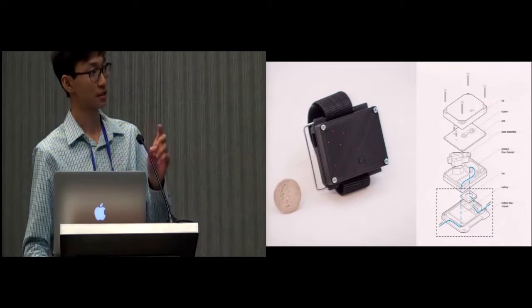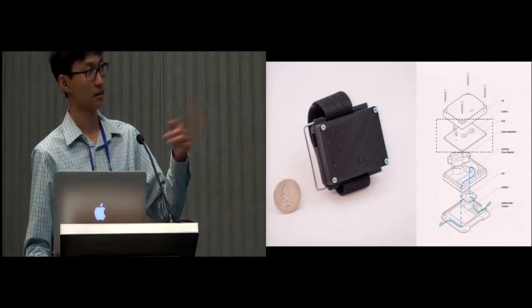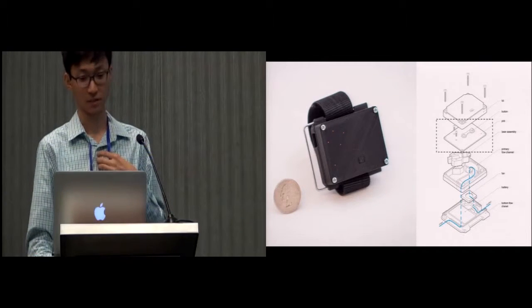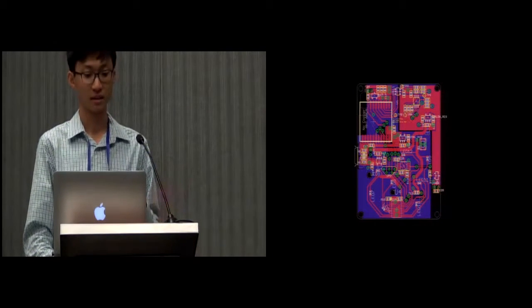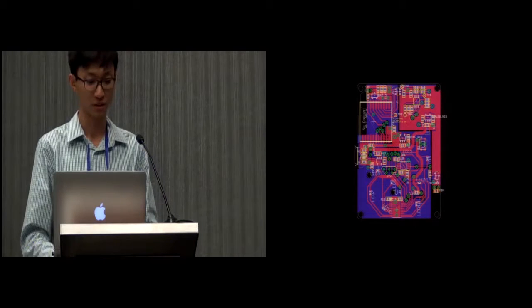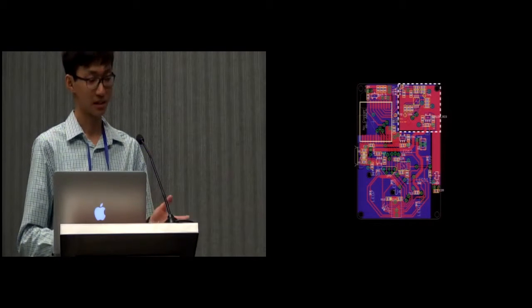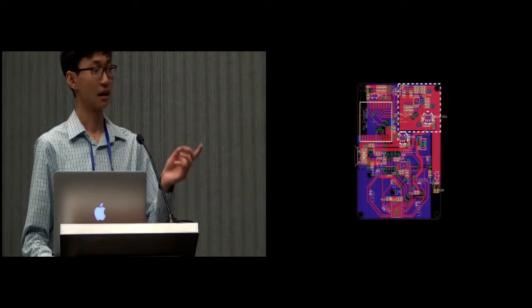Most of these parts are 3D printed with the exception of the PCB, laser, fan, and battery, and I'll talk about the PCB next. So in terms of the electronics design, one of the main points is that we have a high gain photodiode amplifier that's pretty sensitive to noise. So to deal with that, we separated our digital and analog circuitries entirely with separate voltage regulators.